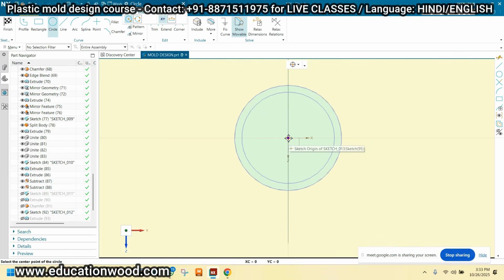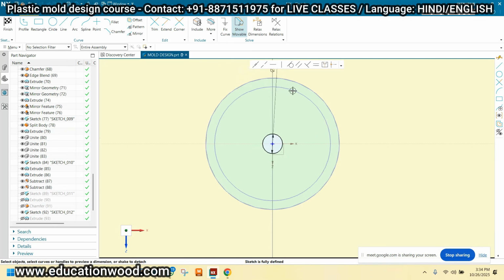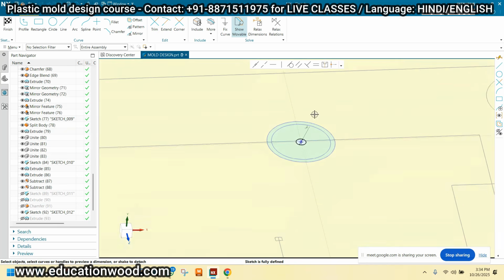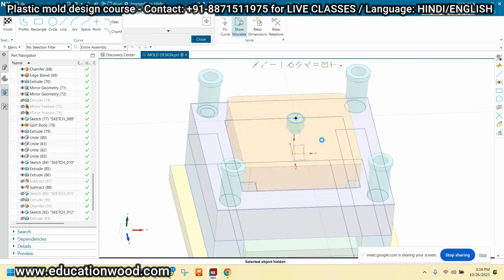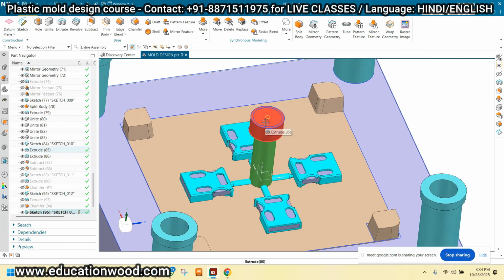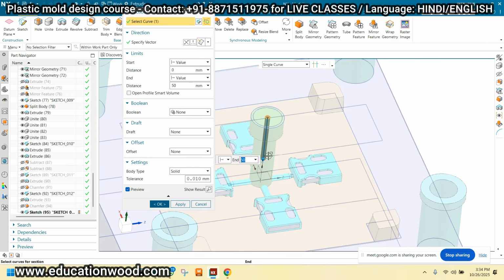And here, diameter aperture hole. Now, if the machine nozzle has an aperture hole of about 3 mm or 3.5 mm, how much should we take here? 4.5. If the machine nozzle has a diameter of 5 or 5.5 mm, we have to take more than 1 mm. Okay. Like this, and just click OK. Yes, 2 to 5 degree. Just hide this.